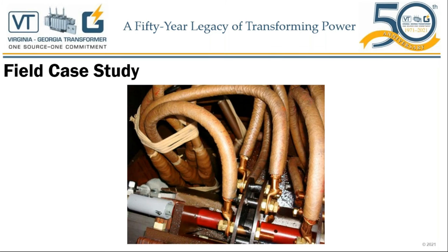Very simply here, if you think about a simple high voltage winding, you have a start lead, then you put the main body turns and you come to the tap section area, then you start pulling 1, 2, 3 leads out. Between each lead, you have 2.5% ratio. And then there's a break between the top and the bottom halves. Then 3 more leads, 2.5% ratio in between. And then you finish the rest of the winding with the second half of the winding. So the connection of the top half and the bottom half of the winding happens via the tap changer.